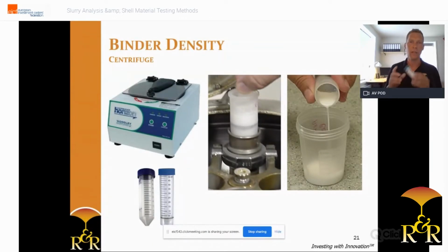The quality of this preparation and this binder is very important for the test reliability. So good preparation and good equipment are very important here. And I can speak from experience, performing slurry analysis on a weekly basis. I've been doing this for almost 10 years. It's not the most exciting job to do. But if the required equipment, training, and the time is supplied to the operators, it will encourage them to do it, and you will see improved slurry stability and cast quality, of course.